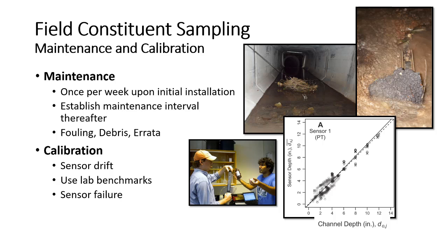Yeah, so there's that debris jam that's hung up on the cable. You can see the cable is right here, and the cable is connected to the back of the sensor back here. And so what's happening is it's kinking that pressure tube. The depth is related to the pressure, and if that pressure tube is kinked, then of course the depth measurement's not going to be right either, right? So we had to figure out how to tuck the pressure cable into the joints between the culverts and tack it down in there with these strips to make sure that this doesn't happen, because it's a storm sewer system, right?